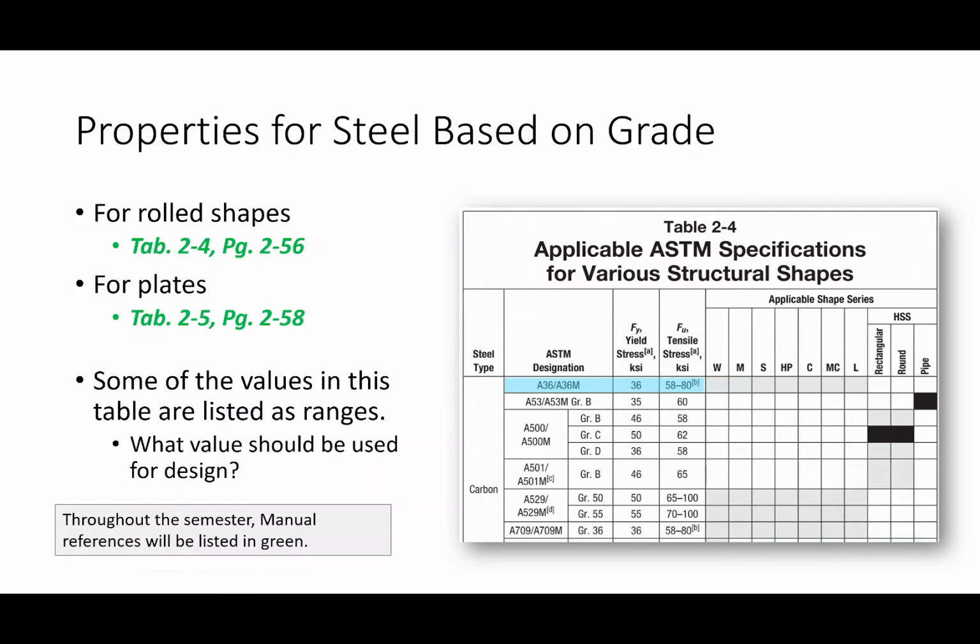But then after the Northridge earthquake, they started doing a bunch of examination of buildings, and they found a bunch of fractures. And they're like, that's not supposed to happen. Wait a minute, that isn't the case. So they broke out some coupons, and they started taking those steel coupons to the lab and testing them, and they found that these elements that were designed, assuming a 58 KSI, were actually experiencing much higher, which is fine. I mean, that's great for regular old everyday, but for seismic applications, the idea behind reporting this range is